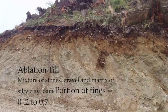All the root activity, the biology of the forest floor occurs in the surface of uncompacted material. The interface between ablation and basal till is often the sliding surface of major slope failures. In terms of surface erosion, some basal tills are so cemented that if you take a backhoe and dig into them, they actually spark. They don't erode easily. You can almost keep a vertical wall as a cut bank and it won't generate much sediment. The unconsolidated materials are a different story.